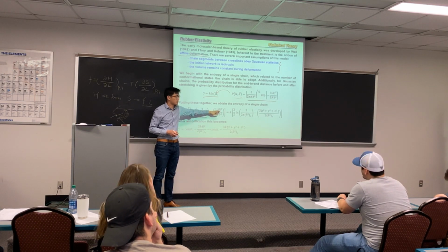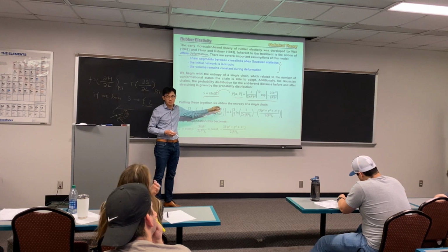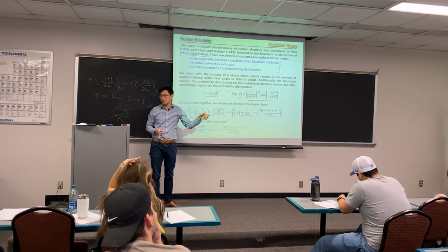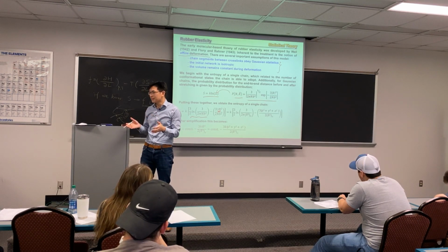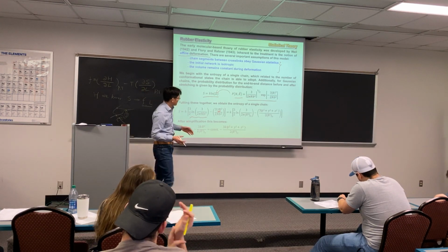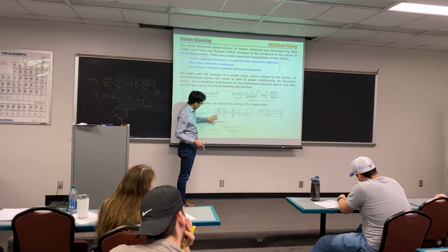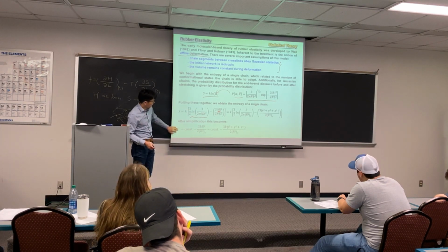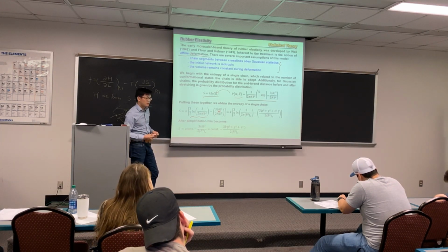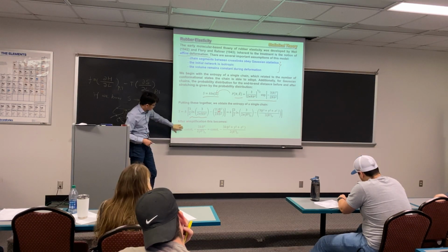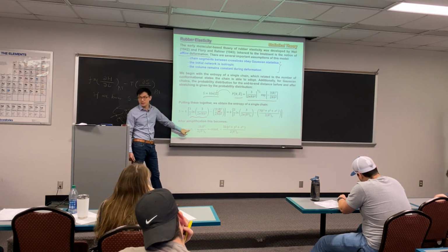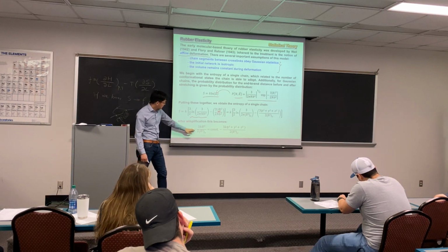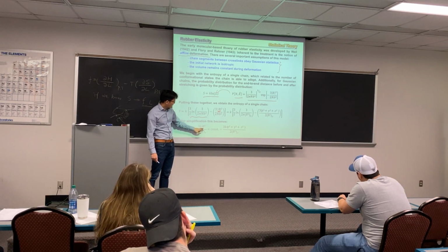And we can be more specific in terms of R. We can consider changes in the X, Y, and Z directions. So if you consider changes in three directions, you can get the value for the deformation of your entropy for a single chain. Okay? So the entropy change for a single chain is given by this equation. Entropy equals a constant, and we explained why it's a constant, minus 3k r squared.